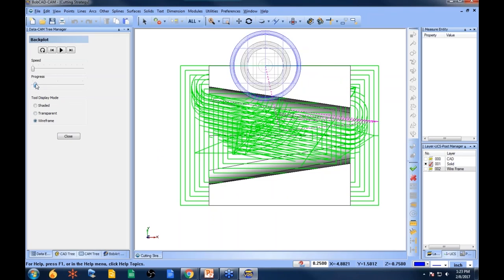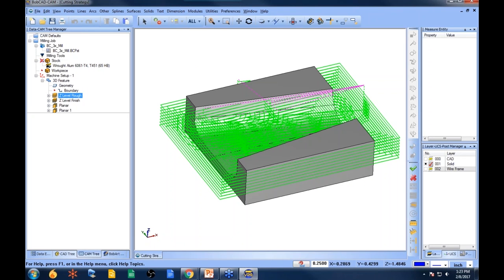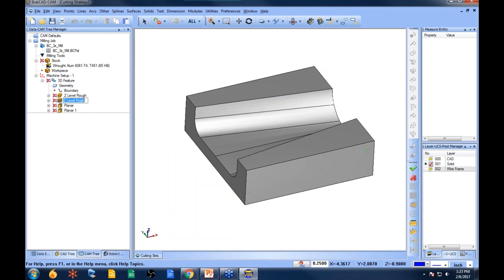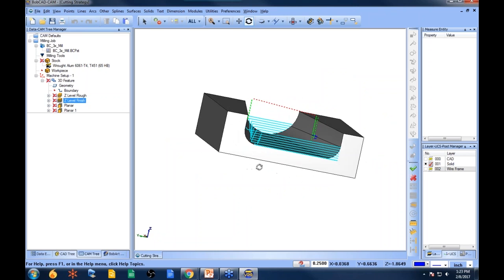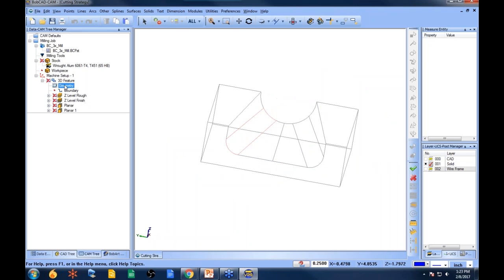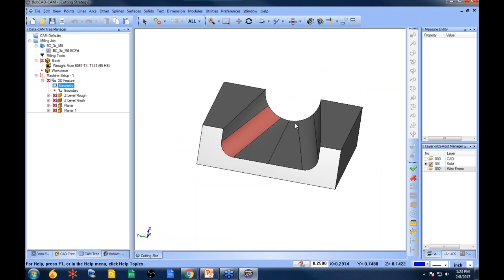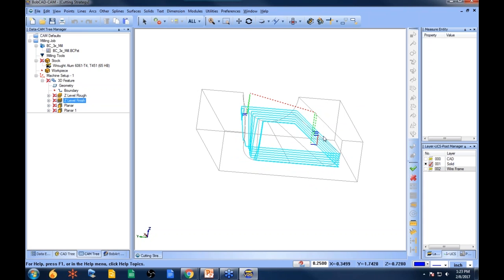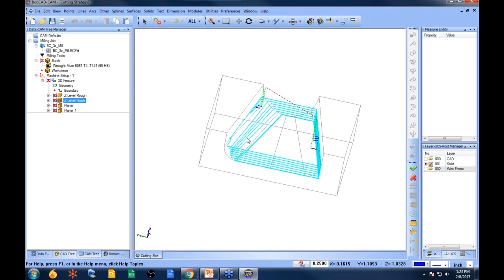Okay, so you can see that the center of the tool is going to go to the stock boundary, which is important to understand. All right, now if we look at the Z-level finish, let me blank all these toolpaths out. If we look at the Z-level finish routine, let's go ahead and compute this one. If you hit S on your keyboard, again, we're applying it just to this surface here. The Z-level finish routine is cutting this surface, but it's also trimming back. I'm not really sure why it's going back over in this area. It's being driven along the surface, but it too is cutting more than what we expected it to cut.